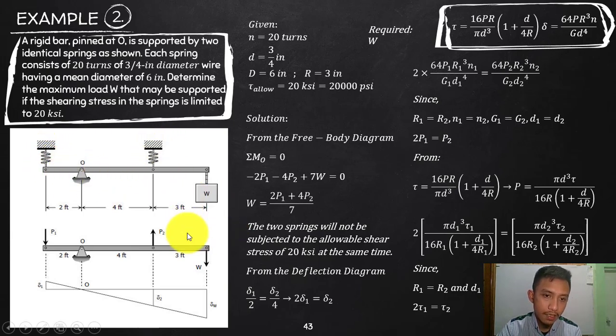Now, if I cut this support so that I expose the forces and get a moment at O, actually I do not need the reaction here. What we are going to focus on is the spring. So I will cut. I need to know the P being handled by each of these springs. So cut that one. That will expose your forces. But since in this scenario this will be compression, this reaction of your spring is going towards the member. This is away, since that will be tension.